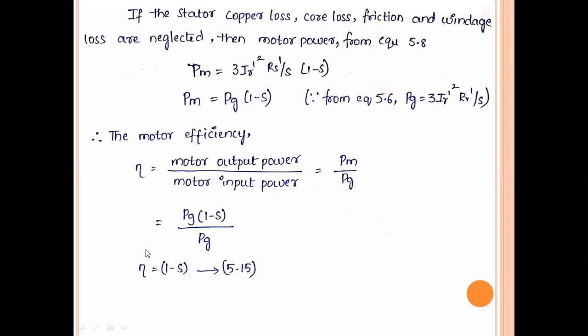And this type of speed controlling technique is used to vary the speed from 0 to base speed only. So 0 to the base speed, or the rated speed of the machine. From 0 to the rated speed of the machine, we use this type of control. And in applications where the power rating is low, in those applications only we will use this type of variable voltage technique.